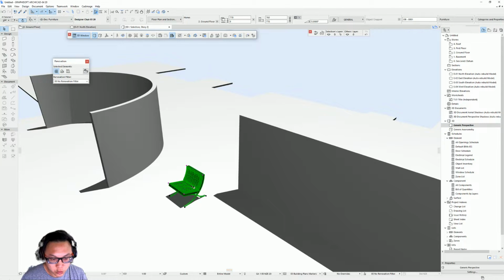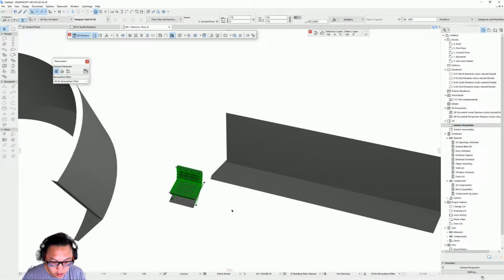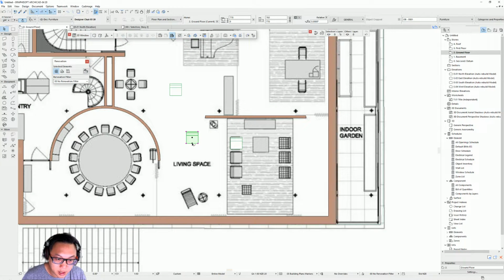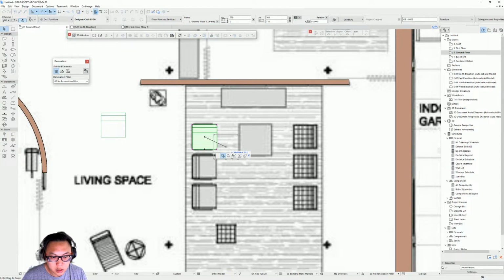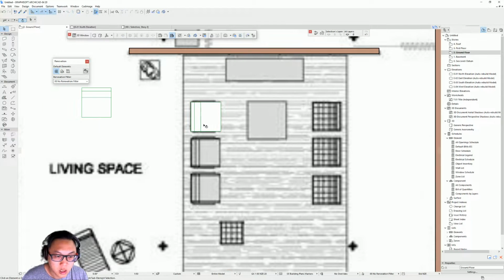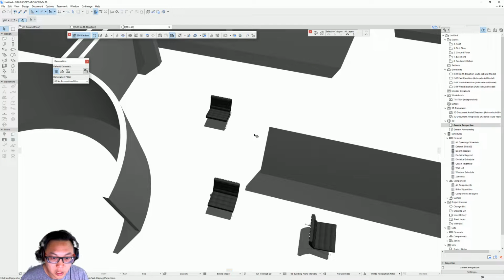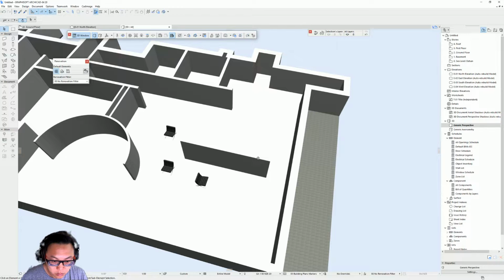Yeah. So here I just wanted to know the direction of the object. As you can see, this one in particular, this is the front. So if you go here, where there's that little point, it means it's facing this way. So you take the object and now I have to rotate it so it's facing the table. Click in the middle and here there's the pet palette, click on rotate, click the center, click one direction, and now you can move it around. So the front now is going to face this way, to the right, and I'm going to type 90 degrees to make sure that it's square. So now if you go back to F5, because nothing was selected, it's going to show everything. The furniture is facing the right direction.